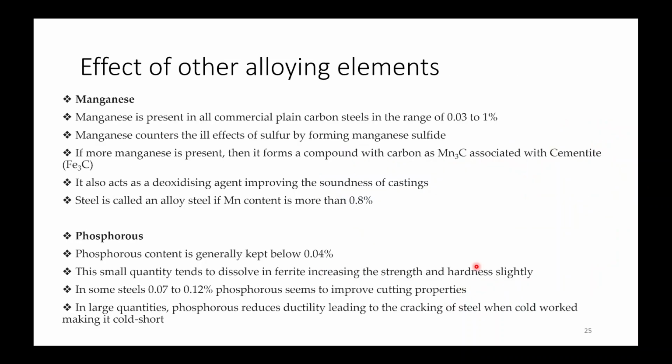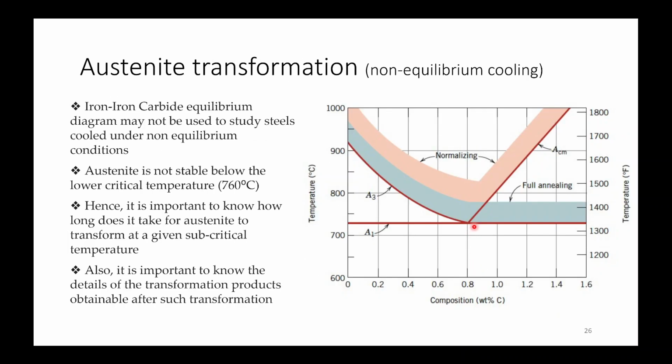Okay, in case of pearlite, it is not a particular, it is at a percentage level, right? It is fixed, like this percentage of Fe3C will be there, this percentage of alpha will be there. That's what is shown in this region when you are forming pearlite. It's a constant line.